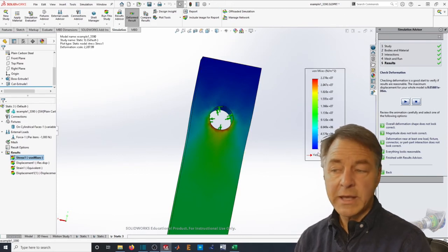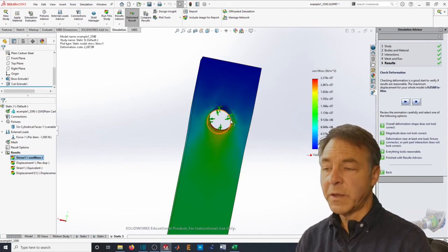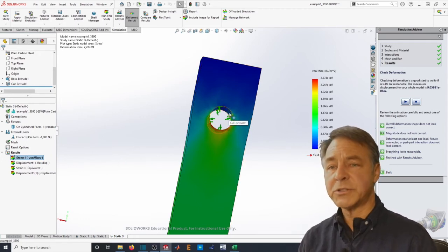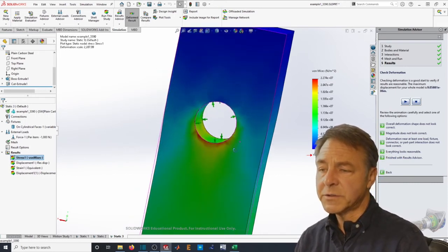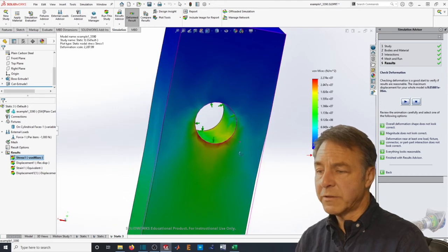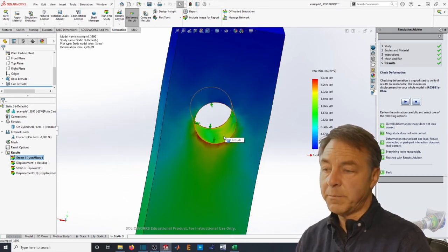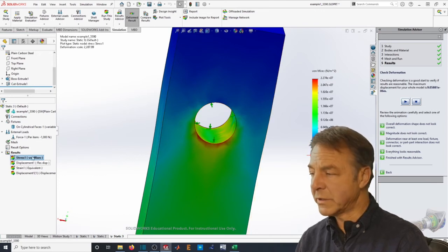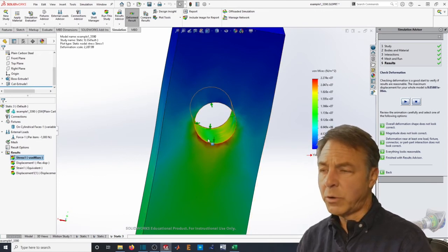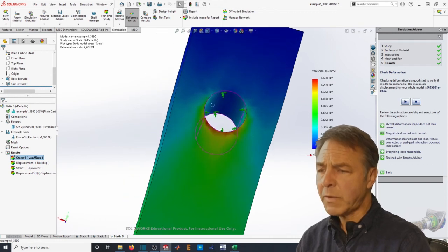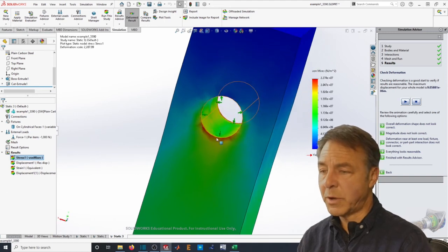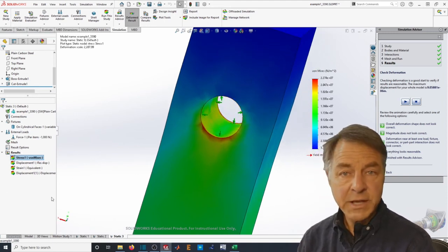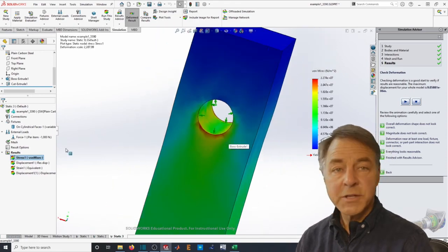Now, I haven't been looking at the magnitude of the total deformation as a check, but that's something you'd want to do just to see how much that change made in the total result. But certainly looking at the details, you could just on face value look at that and see that that is a bit more similar to what one would expect around a hole if the pin is supporting it. And so I'm feeling more comfortable with that approach to the model. I'm not totally convinced yet that this is correct, but I think it's going in the right direction.